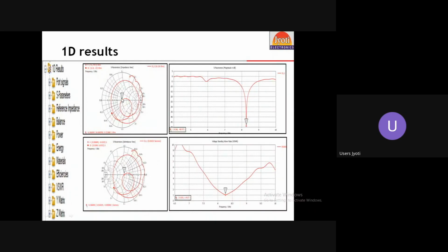But at 0.26, here one value is there. For particularly that value, we can say our impedance is matching, with particular performance at that frequency. You can only follow this red curve. You can't select any other point around the red line. So you can see here the red line is going from here. If you select here, when your cursor goes to here and the 1 point is here, you can see our frequency is changed from 8.2 gigahertz and impedance matching is also changed. So maybe here 8.26 gigahertz is there, maybe at 7 gigahertz frequency it's 50 ohm, completely matched from here.